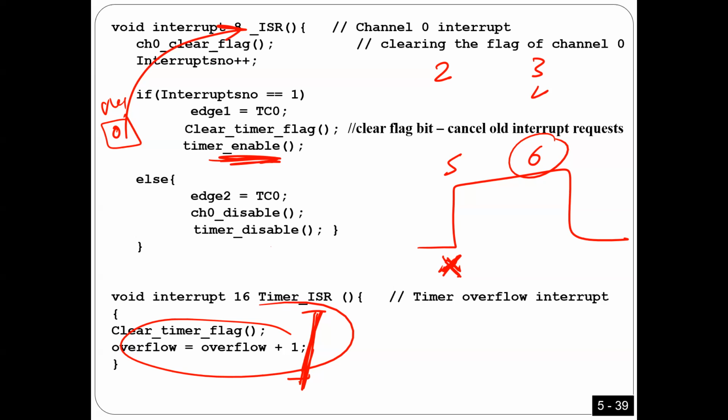Okay, guys. So again, I'm going to say it for the last time. What I'm saying is that we have the flag bit. I want to start counting from this moment. The problem is that the flag bit is already one from the history, because I told you before, the device can request an interrupt. So it's going to put one here in the flag bit, okay? But because it is disabled, I'm not going to serve this interrupt, but still there is one right there, okay?